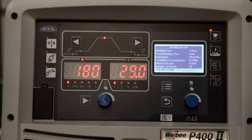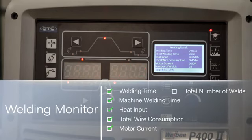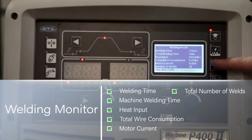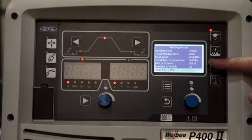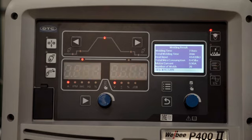One feature that's new to the Welbee II is the built-in welding monitor. After every weld is made, it displays the welding time, the total welding time of the machine, the heat input of the last weld, the total wire consumption, the current on the drive motor, and the total number of welds that have been made with the Welbee.